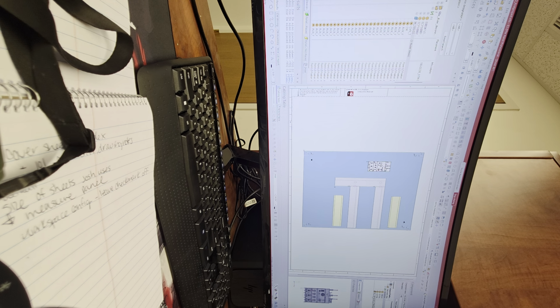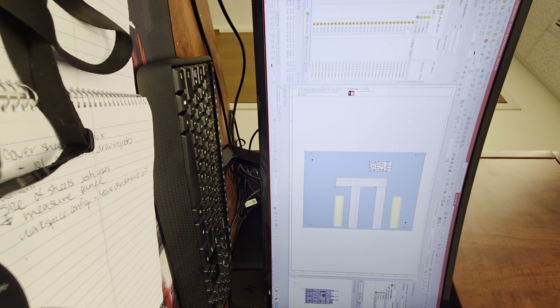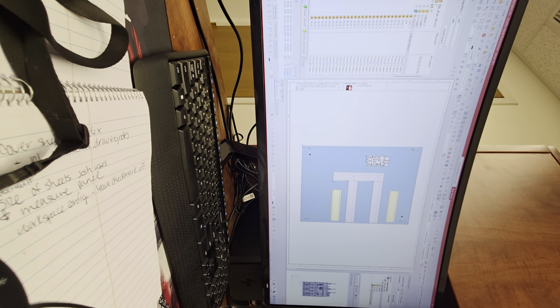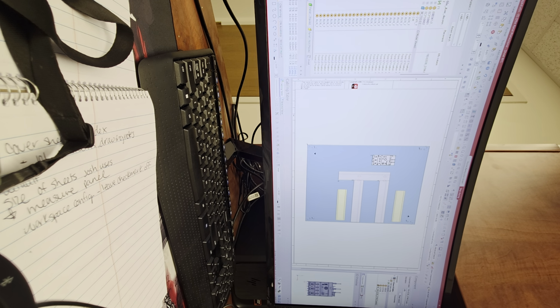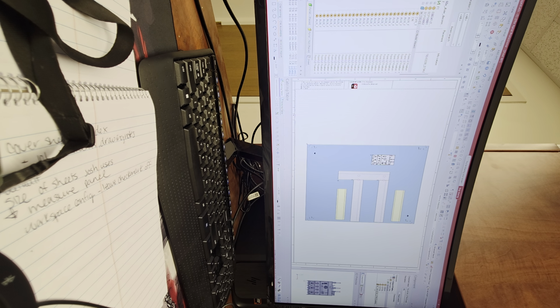Now in your project here, your project will never be automatically updated, and that is purely done out of configuration control reasons. As in, if you just built this project for a customer, you sold it, this is the perfect design, somebody already built a product off of it, you don't want some accidental edit that you just did in the library to be automatically applied to this project. I just call it not kosher from a configuration management perspective.